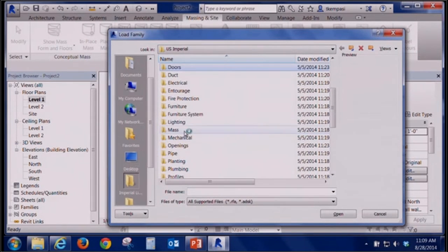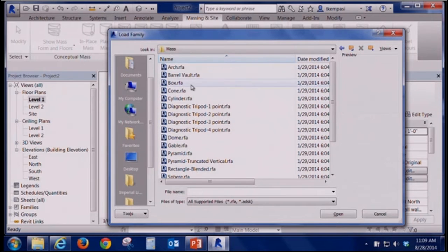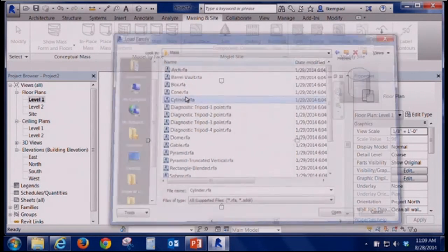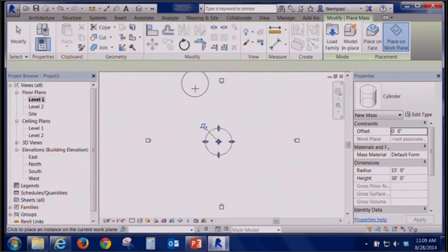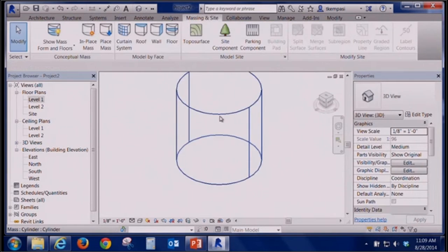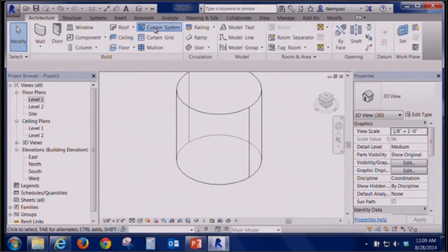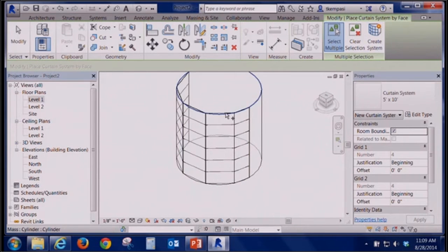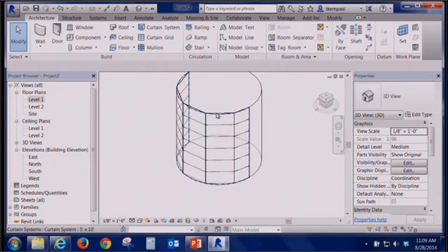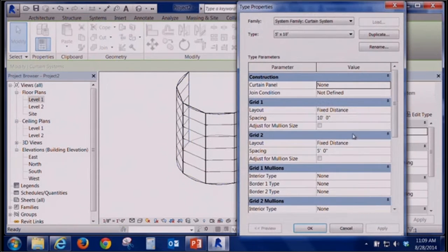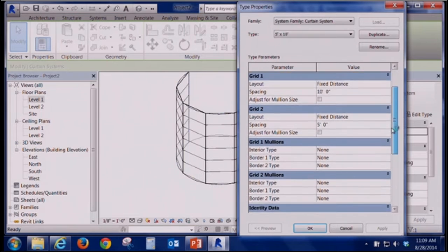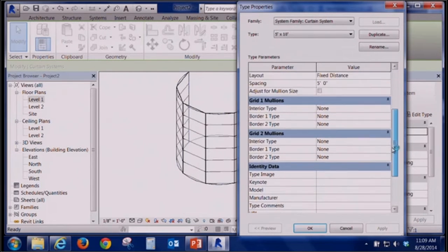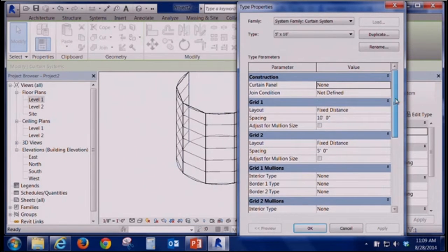And we say, well, you could be better off with your triangular grid, because then you have the possibility to have all your faces flat, even though it curves in one or two directions. That probably also fits well with a quadrangular grid, but if it is a double curvature mass, then probably you want to have a triangular one.